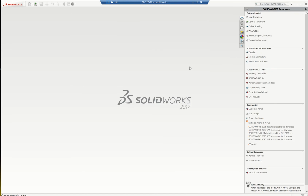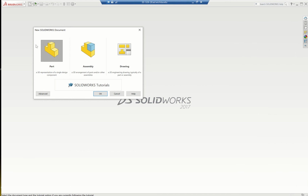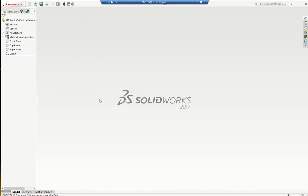I'm going to go ahead and close that for now. And I'm going to show you how I would make this part. Okay, so first thing is I click on New. And we're going to be making a new part. Okay, so I click on Part, press OK, and it'll set up the workspace for me to start building this part.